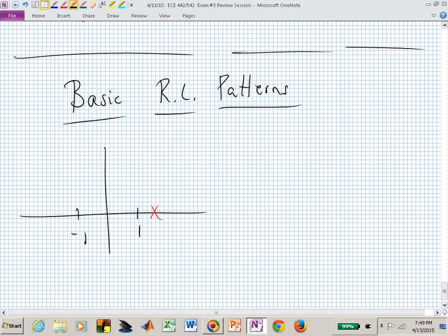If this is now the plant and you know you're in a negative unity output feedback configuration, the root locus is almost trivial, isn't it? It now looks like this. And now the lower limit for stability is there and the upper limit is there. You find those gains and you have your range of stability.